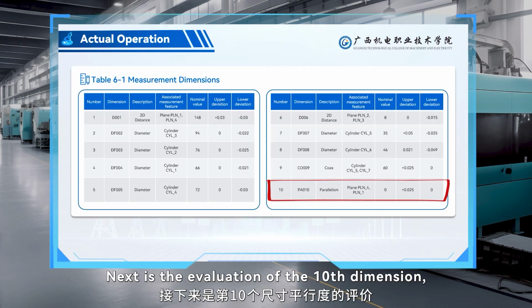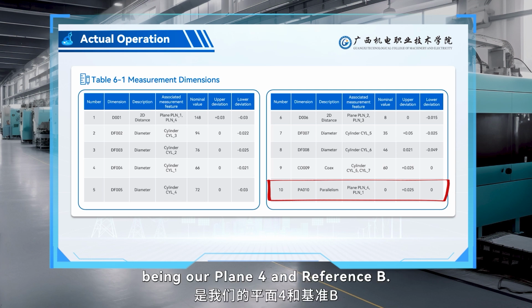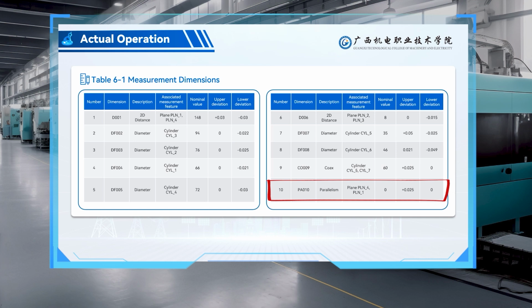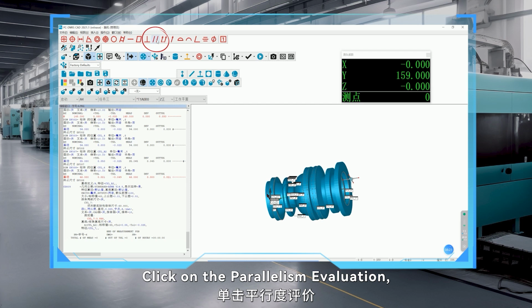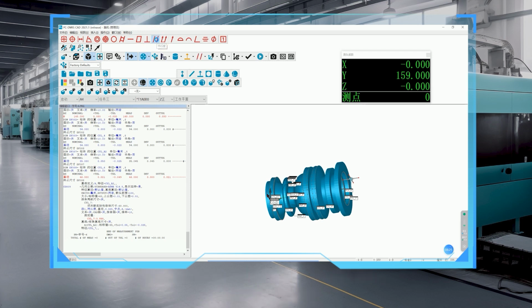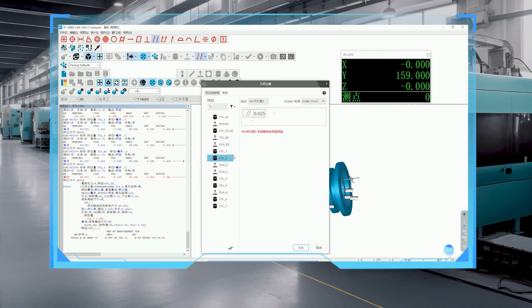Next is the evaluation of the 10th dimension, parallelism, with the associated features being our plane 4 and reference B. Click on the parallelism evaluation, select PLN4, and rename it to PA010.